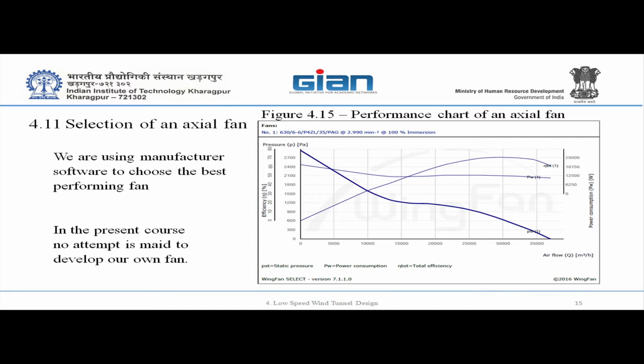Don't calculate too much, don't bother too much, just take the jet power and multiply it by 1.3, another 30% for loss, and that will assure you that you will run the velocity you wanted. Because if you buy the exact jet power, then you'll fall down. That's for sure. But to be more professional, you make it iteratively.